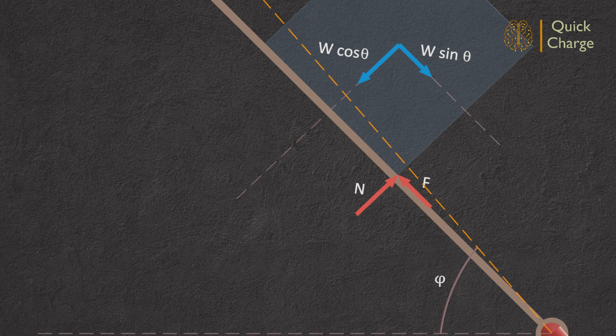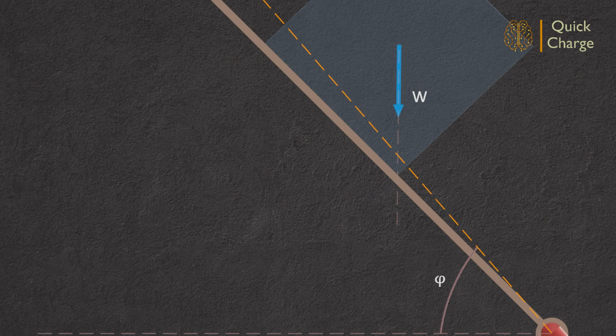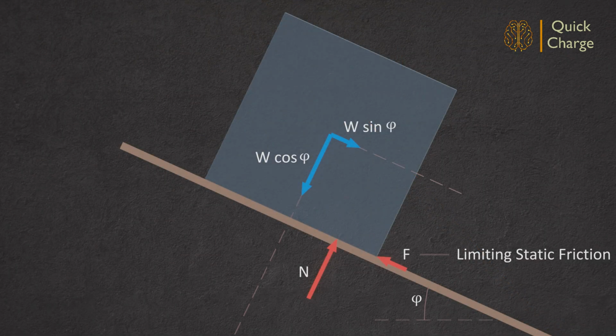Again, in simple words, tipping occurs when the line of action of the self-weight moves beyond the extreme edge of the object. Let us go back to the limiting scenario as per case 2 with a lower angle of repose. We have seen that for this condition, any further increase in slope results in sliding of the box. Consider trimming the forward edge of the box. Assume no weight and center of gravity changes with trimming of the box.